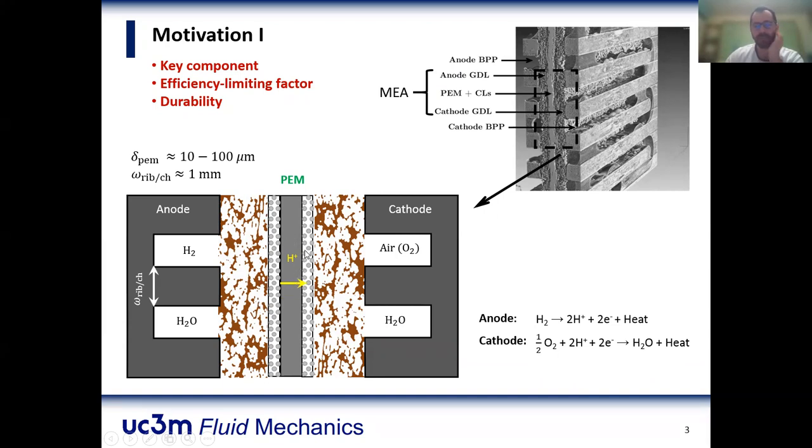In particular, the thickness of the membrane is going to be directly related with the resistance of the membrane, but it is also going to affect the crossover of the species, maybe the water balance in the cell. So we need to understand simultaneously the materials we put there, but also the impact of the thickness. So that's our main goal in this presentation.